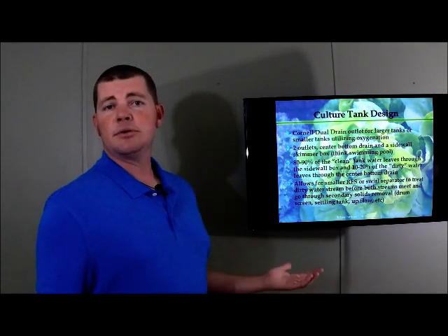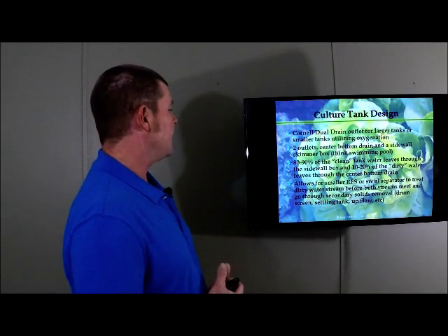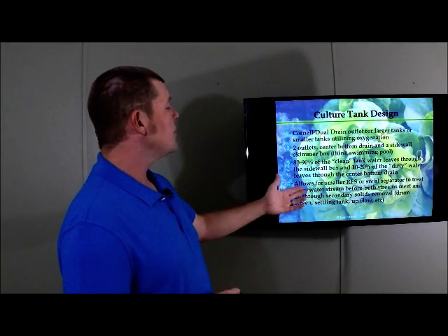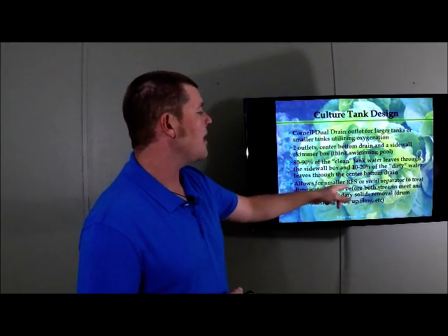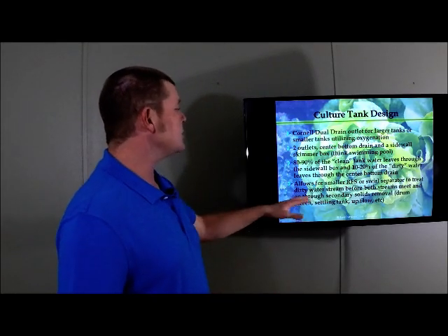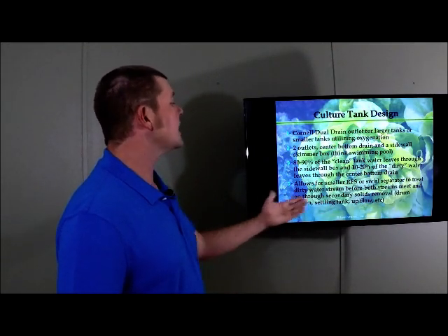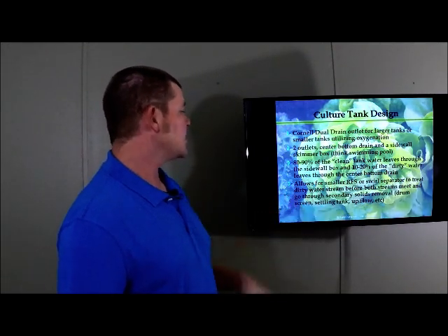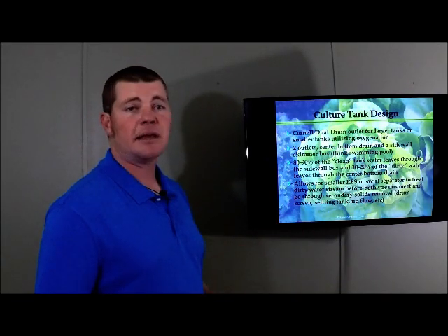Now, why do we do this? What is the advantage of employing this type of system? Well, it allows, for one, for a smaller radial flow separator, that's what RFS stands for, or swirl separator to treat the dirty water stream before both of those streams meet and go through a secondary solids filter, such as a drum screen filter, an upflow filter, or a settling tank.